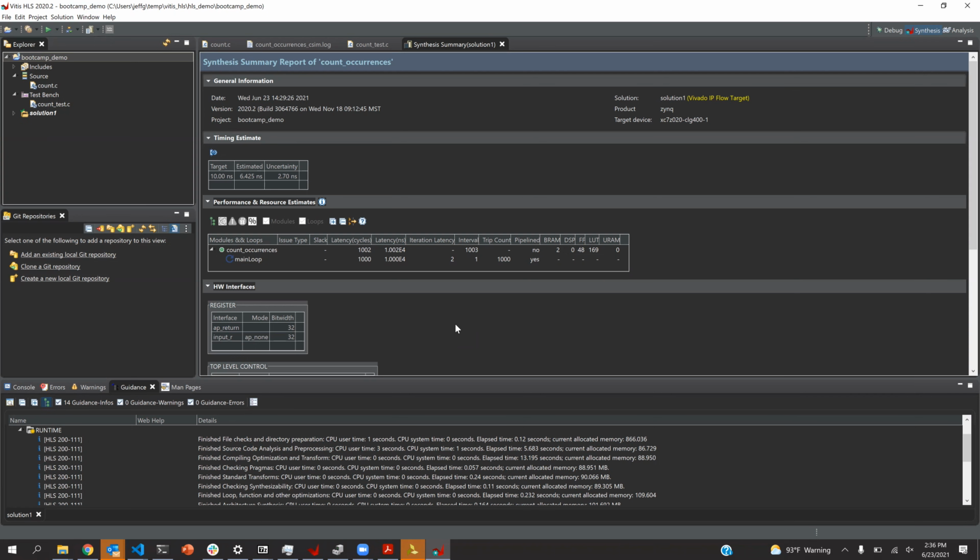Okay, some things, like if you drop a divider down in your FPGA, it may take 50 cycles. You put 2 integers in, it takes 50 cycles for the number to come out. But you can provide new inputs every cycle. So you can have like 50 divisions going on at the same time in the hardware. Okay, so this is quite common in hardware, to be able to pipeline things and overlap them.